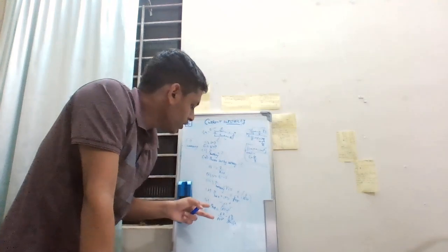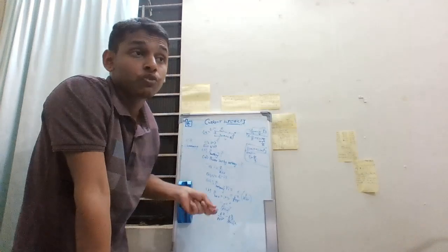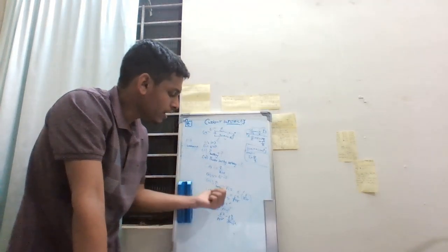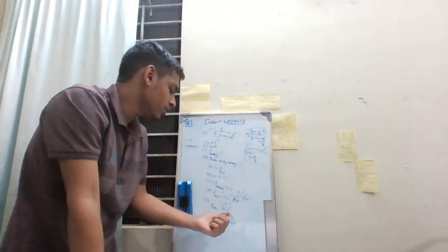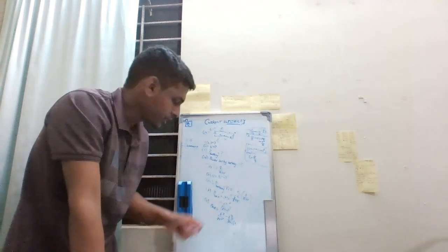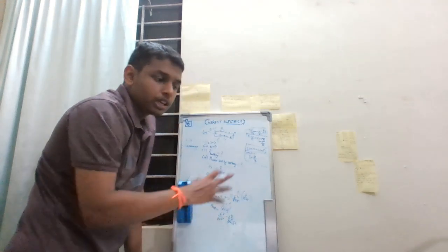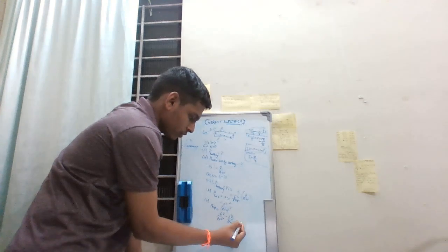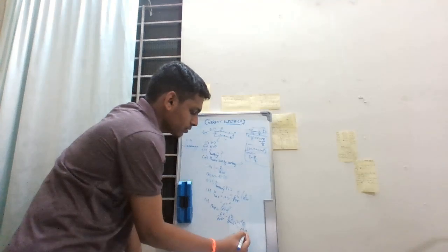So basically what we are doing here is seeing how much the battery is producing and removing how much it has consumed. So here it is how much it has produced, E squared by R plus r, minus E squared r by R plus r whole squared. This is from P lost, I squared r. But if we look at it as a whole, it's just I squared R, so E squared R by R plus r whole squared.